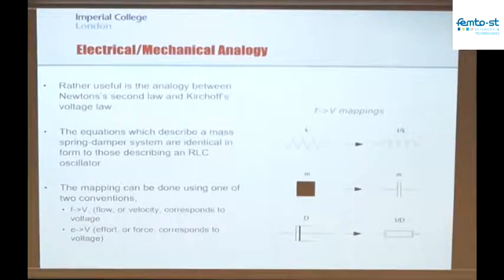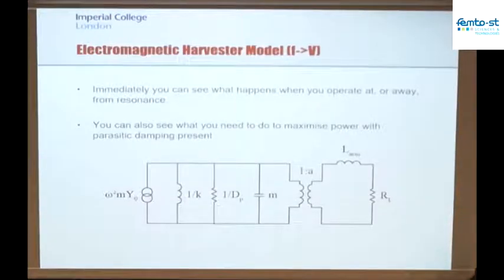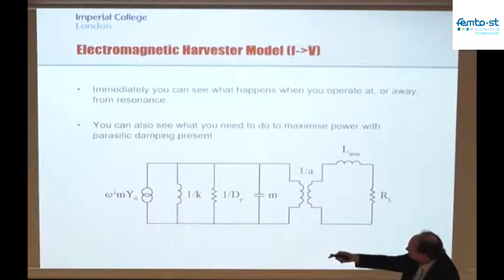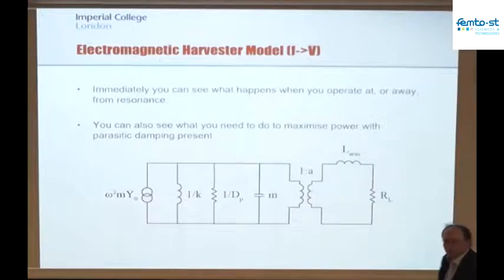But you can do this quite nicely, and of course, if you've got this very simple mapping, then you can produce a SPICE simulation that is extremely fast to run in a circuit simulator, modeling the mechanical system here. So there's a current source, in this case, modeling the mechanical excitation. There's a spring, there's a damper, and there's a mass, all modeled as electrical equivalent components.